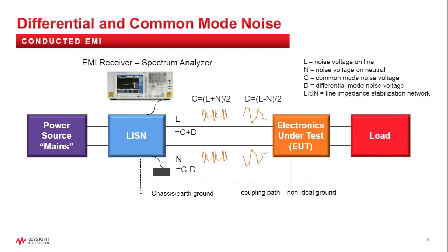Its job is to separate the source from the device under test, the electronics under test, keeping any noise that's conducted out of the device under test from getting onto the power source, but also to provide a standardized measurement tap point so that I can connect an analyzer and everyone can agree that from my certified lab to your certified lab, and from my simulation setup to your simulation setup, I'm tapping into a standardized point of reference to pick up this noise.